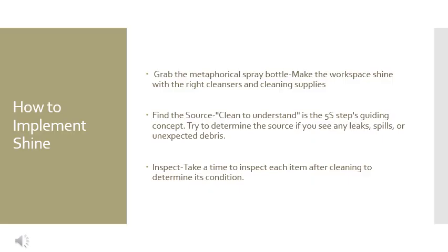If we notice any leaks, spills, or unexpected mess, don't just wipe them away. Take the time to investigate the cause, which will eventually help us prevent these issues from happening again in the future. Finally, don't forget to inspect everything after cleaning. Regular inspections are crucial for catching any wear and tear early on, ensuring that our equipment stays good and functional.